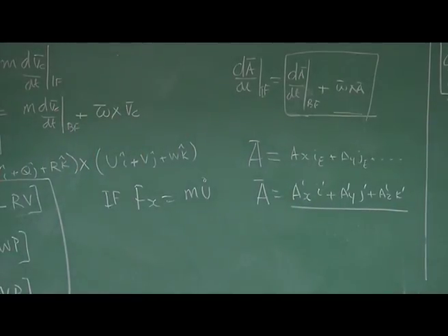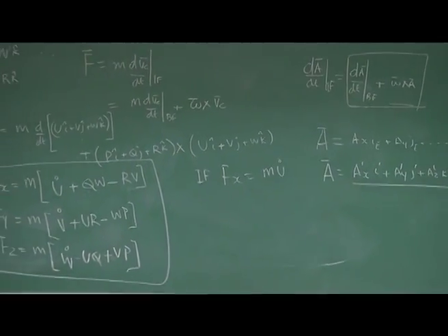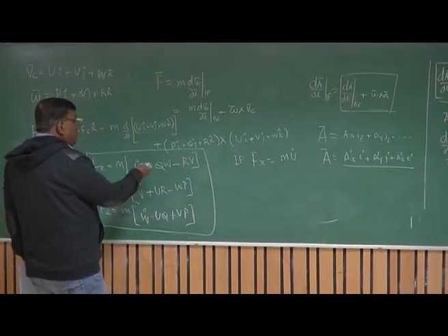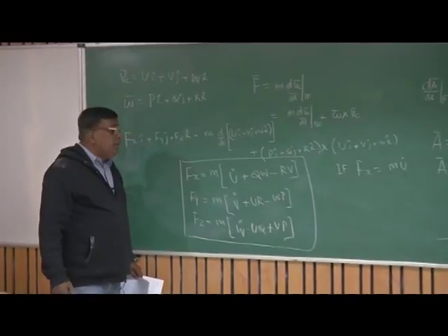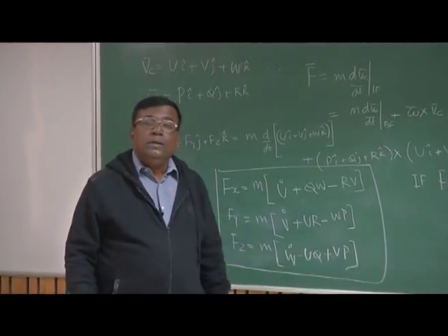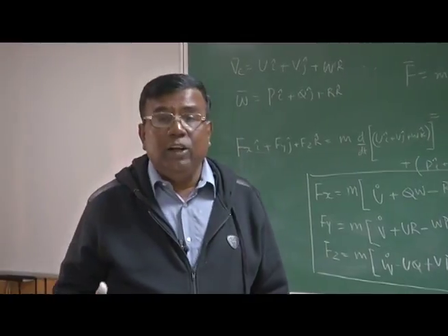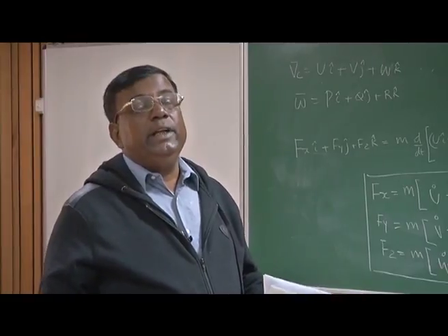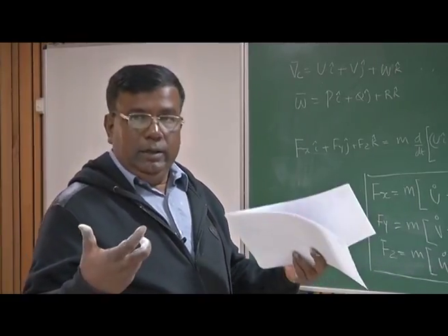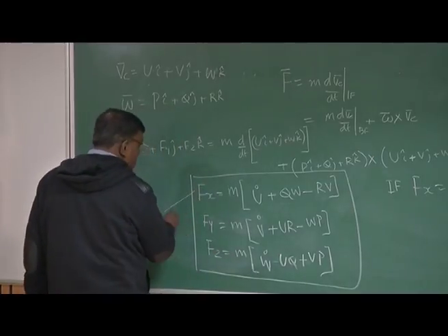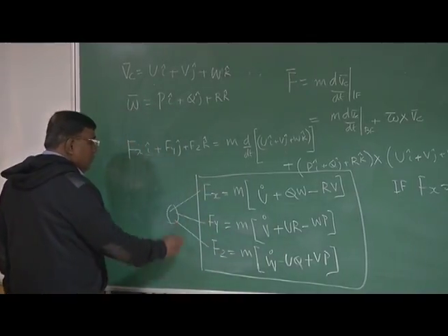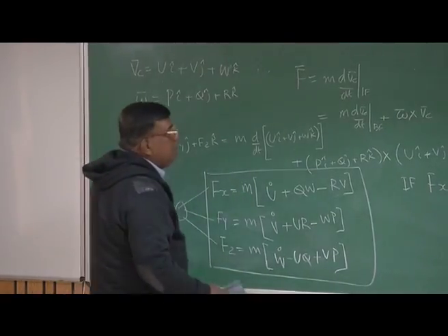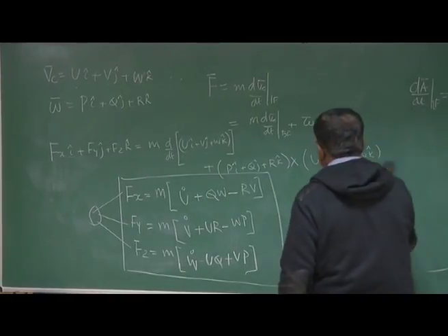So this is what we are doing. We are taking that vector, which was with respect to the inertial frame, and now writing it with respect to the local frame. Now you can see if I put a sensor in the aircraft, I can easily get u, v, w because now it's body relative. And aerodynamic forces will be easily computable because now u, v, w are air relative speed. Then the next question will come, what is Fx, what is Fy, what is Fz? We will discuss that. Before I discuss Fx, Fy, Fz, let us complete the moment part.